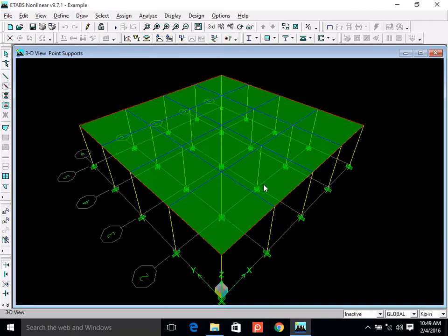So your slabs can have area loading, which can be live load, which can be dead load. It can be any type of dead load, maybe partition load, maybe floor finishes, and if it is the roof, then roof details. So you need to have these loads ready with you, that from the architectural plan, you need to figure out what is the loading for a specific panel.